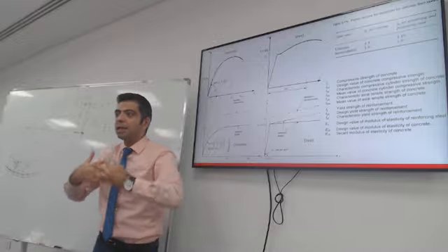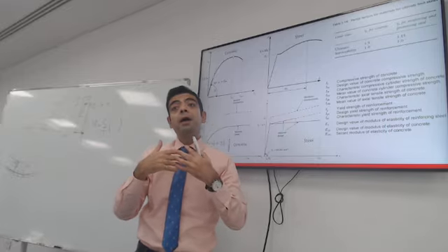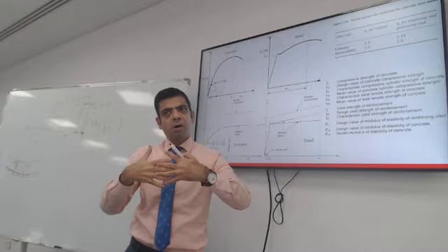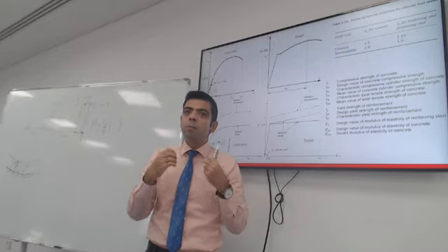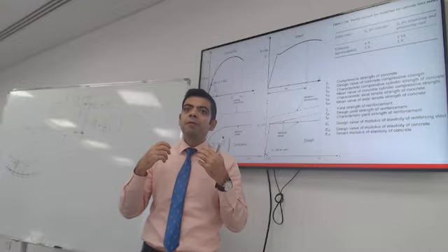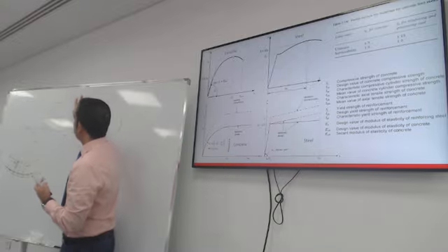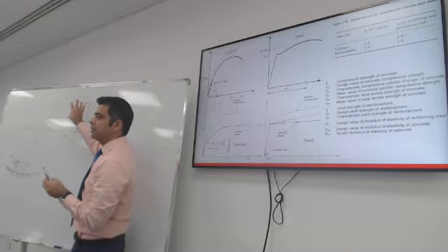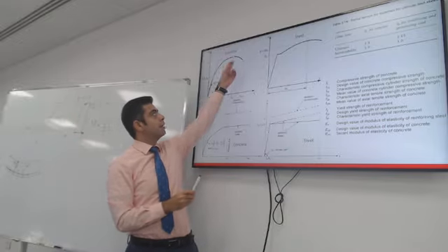It will happen suddenly. It will not give occupants of the building ample warning that there are some cracks, like wait a minute, there's something happening. Concrete is more brittle. It will fail suddenly. So you don't want compression failure to govern the design. Therefore, you don't want concrete to reach that level first.